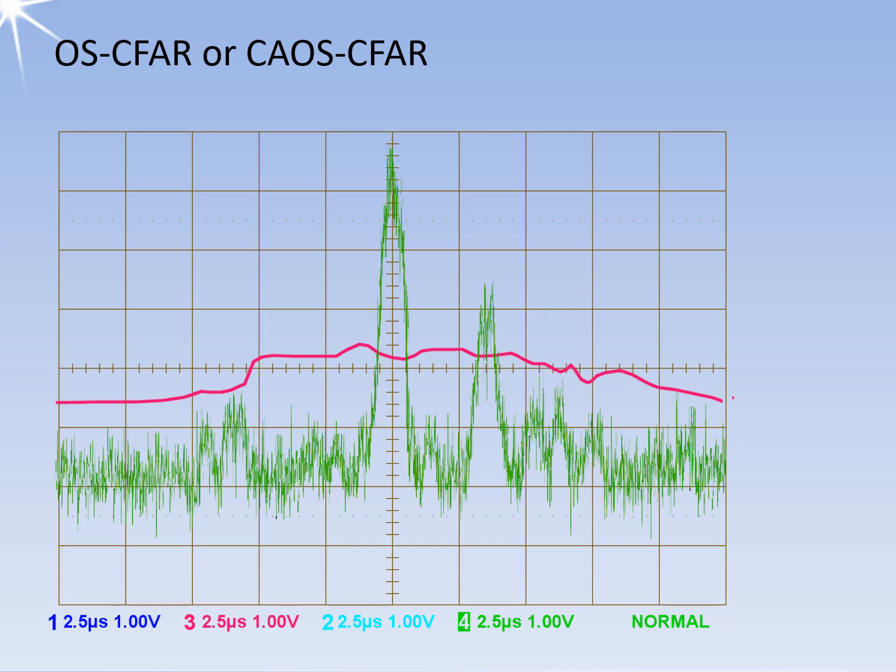delay line are sorted in size. A certain number of the highest values are excluded from further processing. An average can be formed again from the remaining values. CAOS-CFAR, or other weightings can be carried out, e.g., depending on the average noise level. Here, too, a separate separation into preceding and following cells can be carried out. Their results can be selected again as greatest of OS-CFAR or smallest of OS-CFAR before further processing.